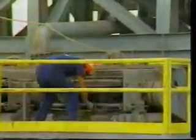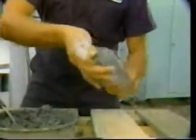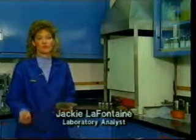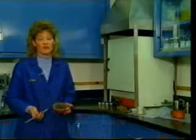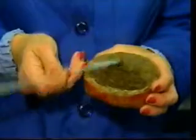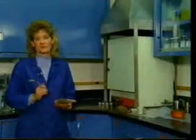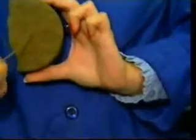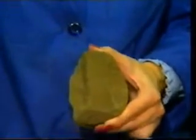For example, to determine the effects of changing water saturations, rock samples are taken from the completion interval and sent to the lab for analysis prior to completion work. Typically, we receive samples from all over the world, and one of the questions that we're asked is, do we need to gravel pack this well? In the case of this sample, you can see it's very unconsolidated, and the answer is obvious. Yes, this well will need to be gravel packed. The hard part comes in when you get a sample like this that's basically consolidated, and we'll have to have additional tests run to determine what's going to happen to this well after it's put on production.